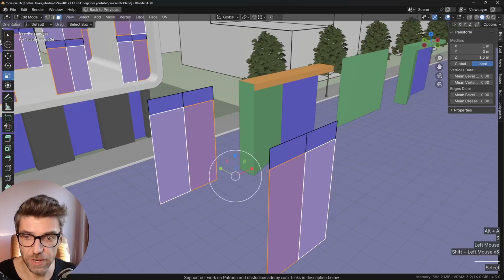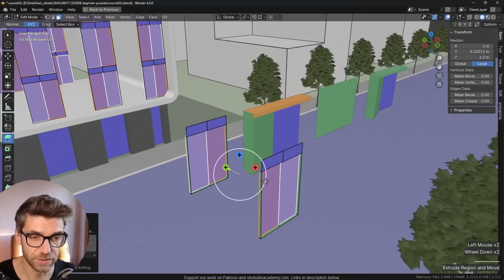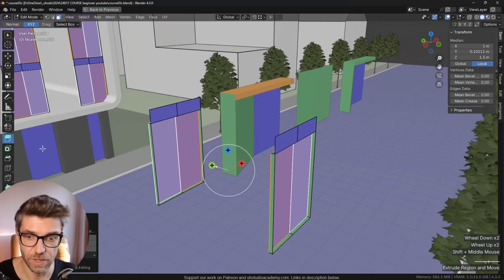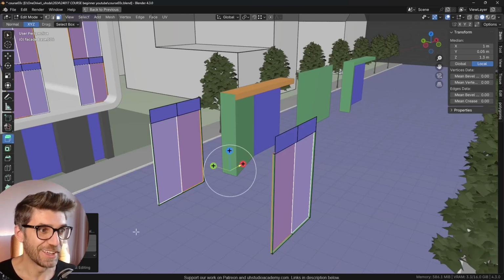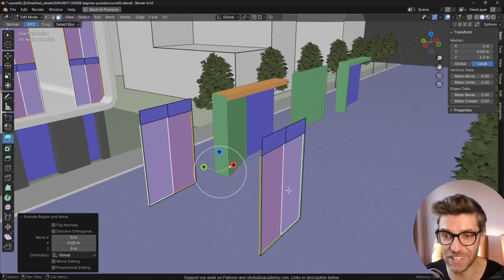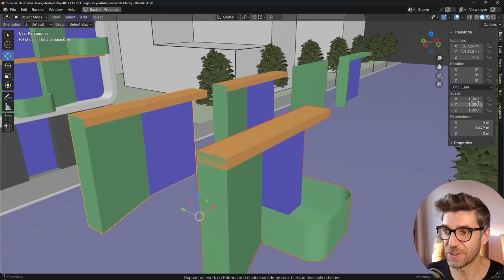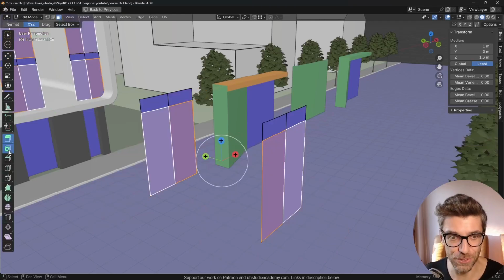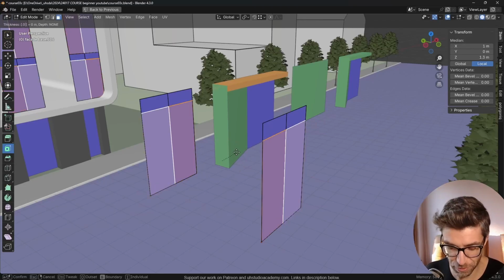And now with these two elements, we're going to extrude them slightly in like that. It can be much less, 0.05. And I love the fact that people say that Blender is not precise, because here I am putting exactly the things that I need in there, right? So yeah, anyways, I like to mention that. Before I do that though, let's inset these. Now that's where it gets, okay, we did apply the scale in the previous video at some point, because otherwise our insets would be wrong. So now we can inset and type in 0.05.